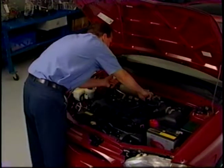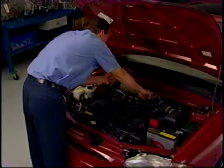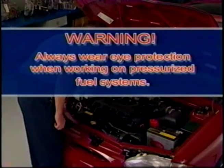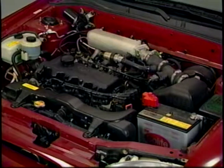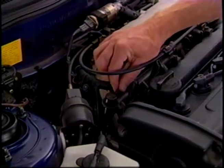Diagnosis of drivability concerns that are other than ignition misfires start with a test of the fuel system pressure. Always exercise extreme caution when working on pressurized fuel systems and always wear eye protection. Depressurize the fuel system by removing the fuel pump fuse and then start the engine. Allow the engine to run out of fuel and stall, then install the fuel pressure gauge. Reinstall the fuel pump fuse and test the fuel pump.